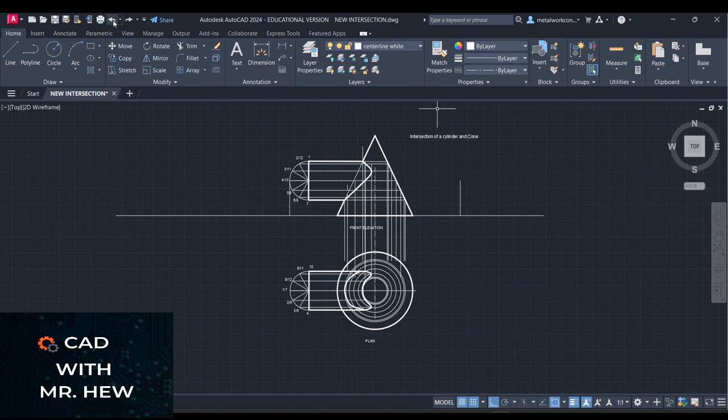the 45-degree lines, okay? So if you have your T-square and your set square, we draw those vertical lines here. So this line will be coming from where the semicircle is, right? And this line is the same distance that we have from this line drawn from the semicircle to the base of the cone, represented by a triangle. Right, so this distance from here to the end of the triangle is the same distance from this line to the end of the triangle.